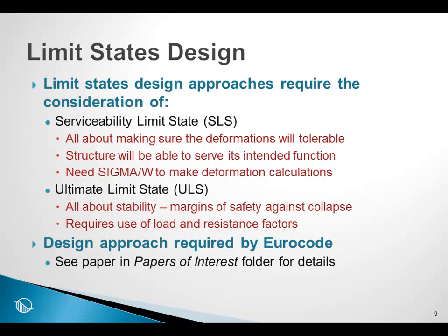For those of you who are working in the context of the Eurocode and are required to work in terms of limit states design, you may be interested in a document that we have produced, and the title is Using GeoStudio in the Context of the Eurocode. This document is in the Papers of Interest folder and is there for your convenience if you need to work in this context. But the point here is, to work in the context of limit states design, we must use sigma W type of analyses.